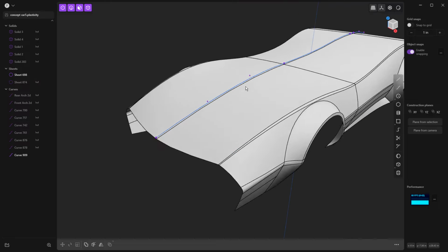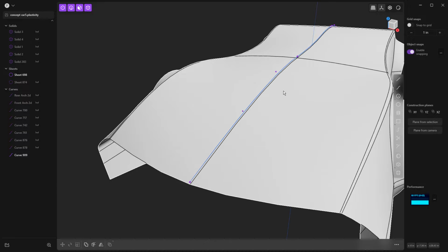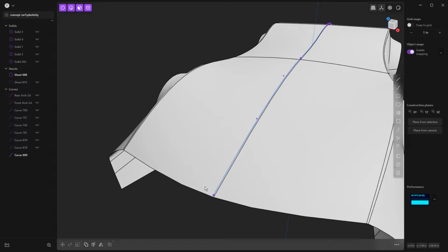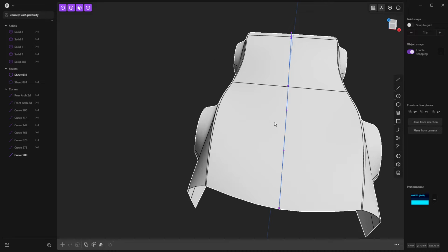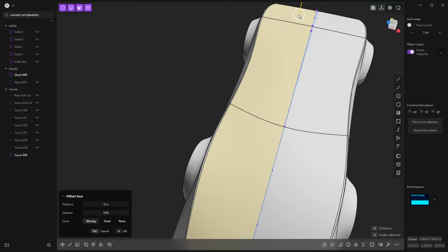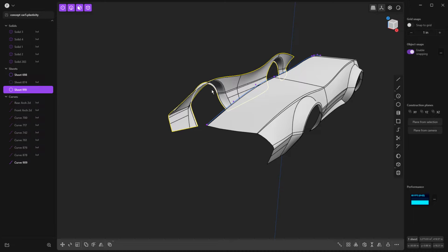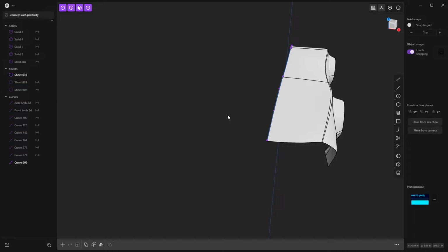And that 1/2 inch, it's probably a bit extreme, but that 1/2 inch is going to be where that seam is. And then what I want to do is split the middle of this on both sides. The way I'm going to make that happen is I'm just going to get rid of the left side, by Shift Delete to get rid of that section, which will break this apart from it. And then I can just hide that section for right now. So we've got this hood piece I don't need anymore because I think we're past that. And then we've got this right-hand section.